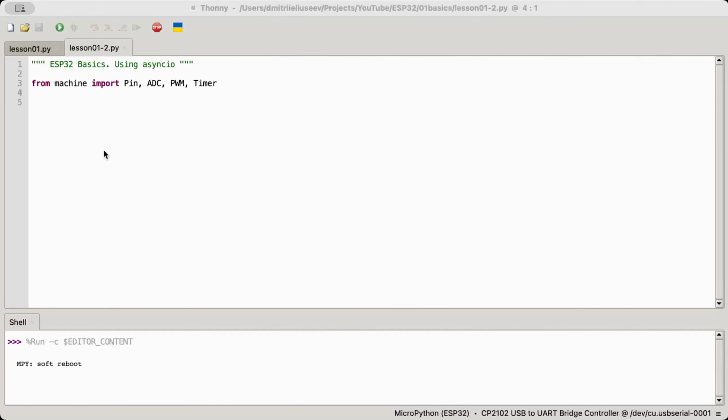This is a very powerful approach for the desktop, for example, for a web server that can handle hundreds of connections, because we don't have a CPU with hundreds of cores. And of course, it is important for the ESP32 because technically ESP32 has 1 or 2 cores maximum, so we can do many tasks. And in my previous code I used the hardware timer, but with Asyncio we don't need it, so let's see how it works.